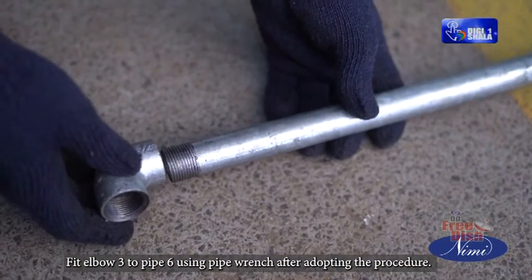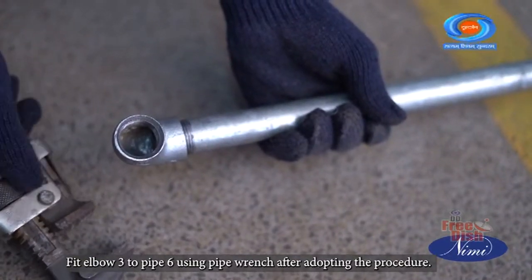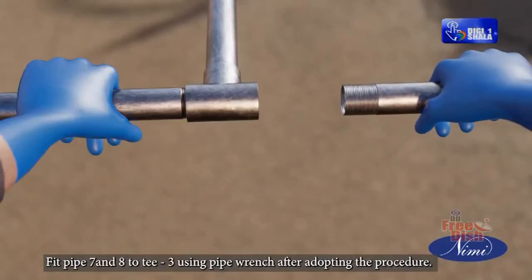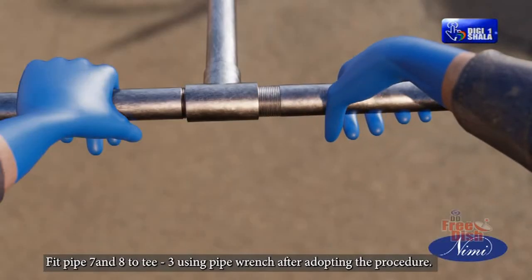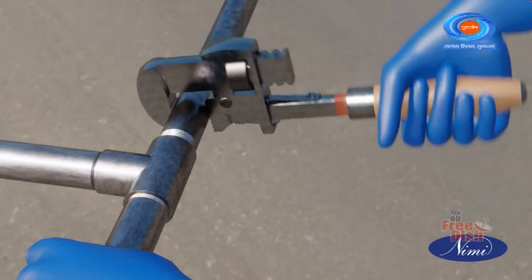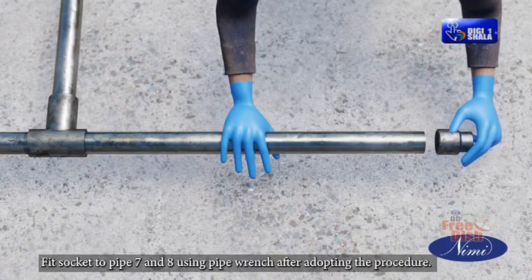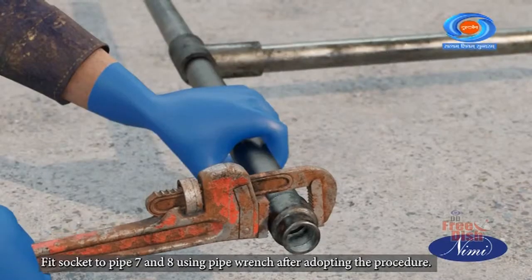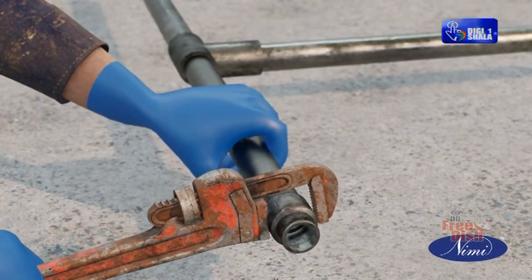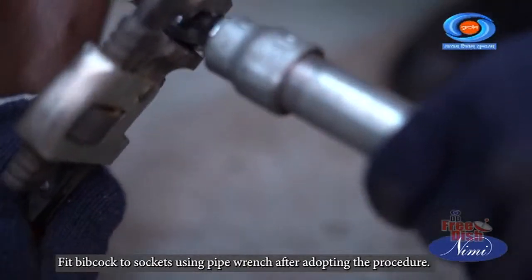Fit elbow 3 to pipe 6 using a pipe wrench after adopting the procedure. Fit pipes 7 and 8 to T3 using a pipe wrench after adopting the procedure. Fit socket to pipes 7 and 8 using a pipe wrench after adopting the procedure. Fit bibcock to sockets using a pipe wrench after adopting the procedure.